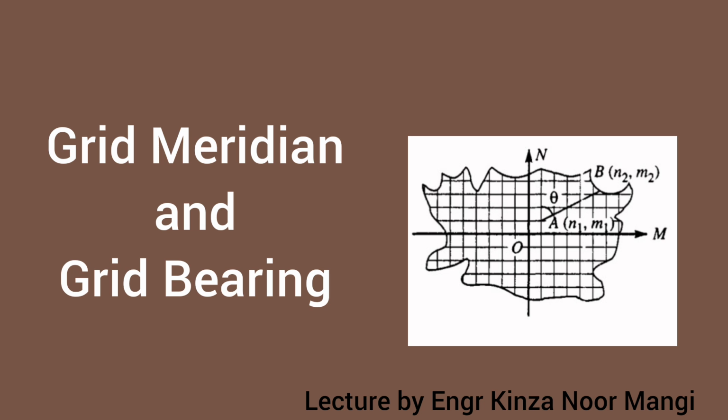Now coming to the grid meridian. For preparing a map, some state agencies assume several lines parallel to each other, and all those lines are parallel to the true meridian for a particular zone. These lines are termed grid lines, and the line which is situated in between is known as the grid meridian. The bearing of a line with respect to the grid meridian is known as the grid bearing of the line.